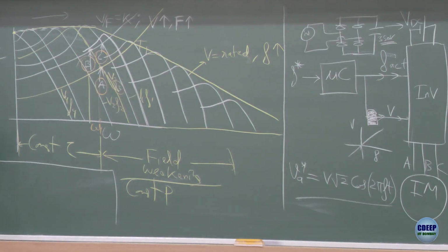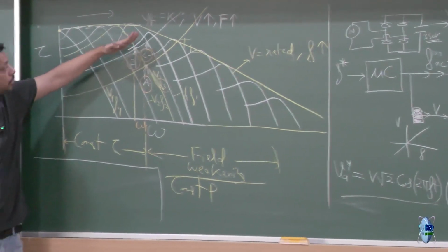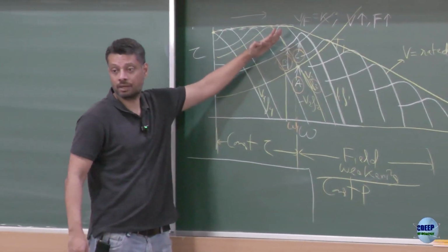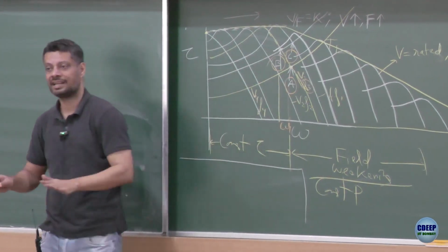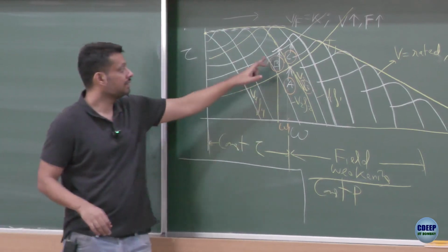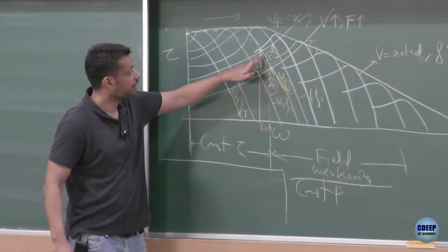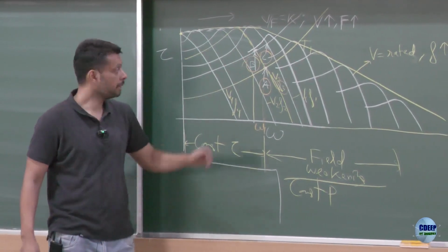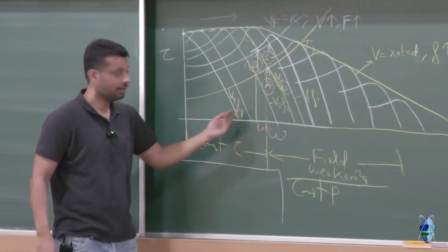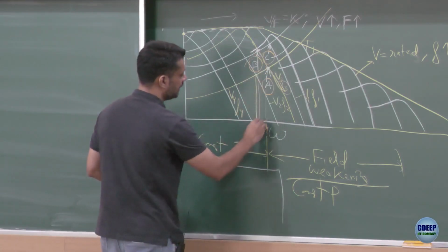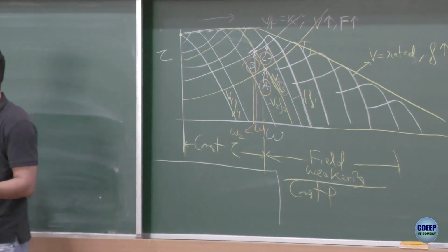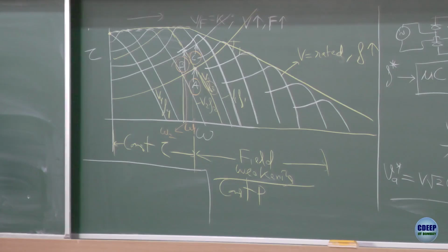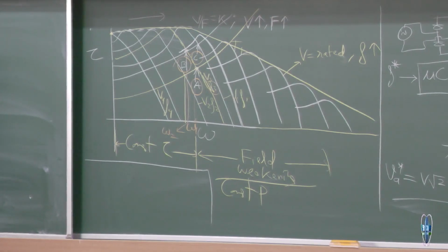right? Somebody changed the load characteristics. Load characteristics move from this guy to the white one. It moved upward. You increase the load, right? Now for the same source characteristics, because the source is now settled, the speed has settled, the frequency is the same, the intersection point has moved from this point to point B. But at point B the speed is a little less than A. At point B the speed is, let's say, omega 2, right? Speed has reduced. Now if you have no clue of the actual speed, then nothing will happen. You will operate at omega 2.